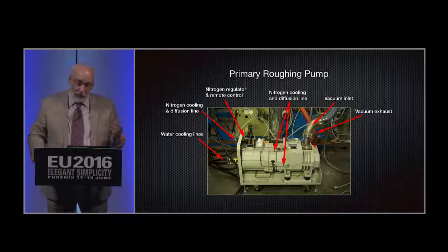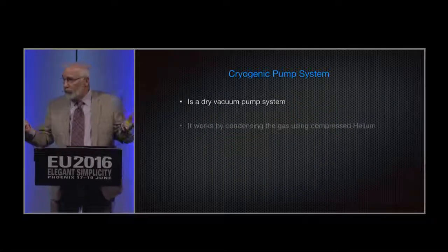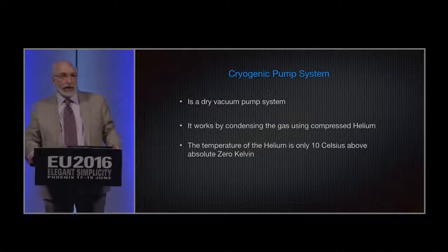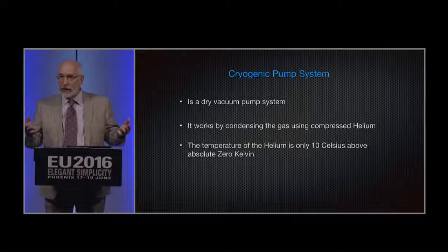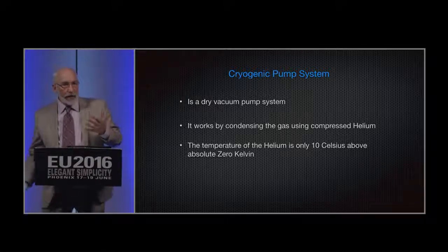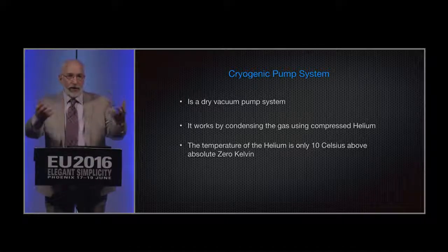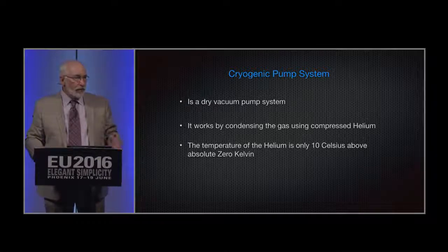Nice pump. Expensive pump. It's a really good pump. It's a dry pump, by the way. Now that's important because we don't want any hydrocarbons in the chamber other than what we want to put in there. We don't want oil bleeding back through the pump into the chamber, which we think we may have had a problem with in phase 1.